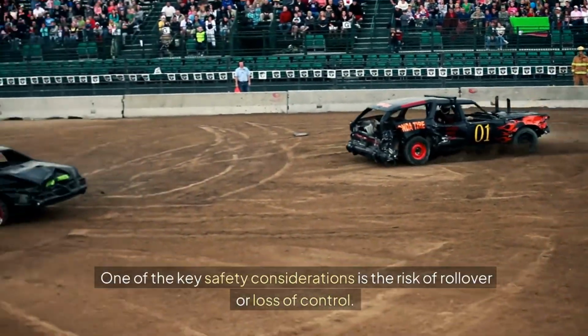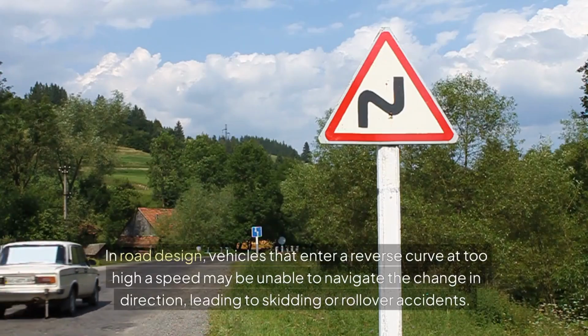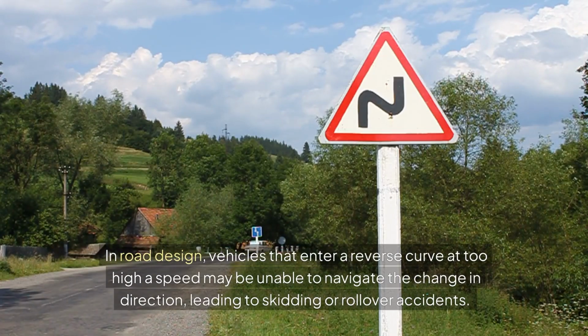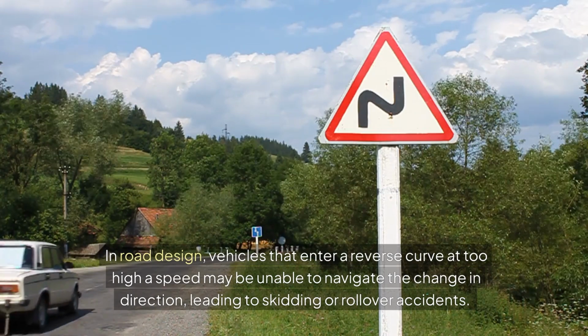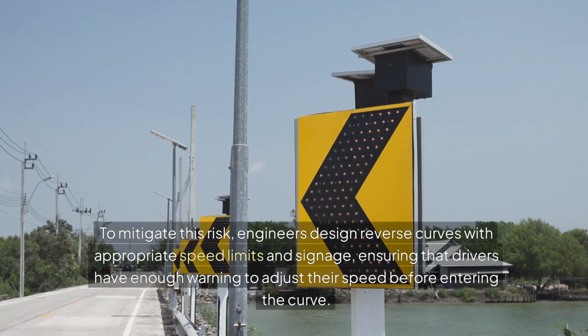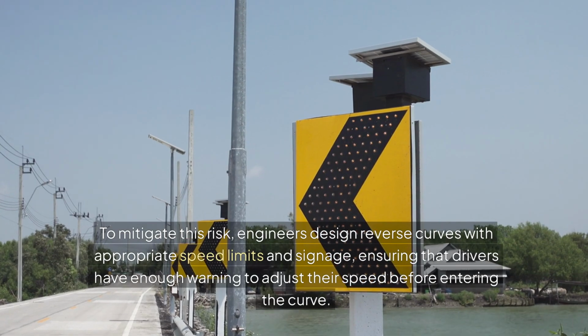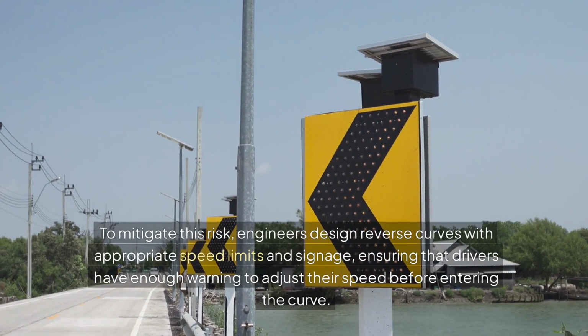One of the key safety considerations is the risk of rollover or loss of control. In road design, vehicles that enter a reverse curve at too high a speed may be unable to navigate the change in direction, leading to skidding or rollover accidents. To mitigate this risk, engineers design reverse curves with appropriate speed limits and signage, ensuring that drivers have enough warning to adjust their speed before entering the curve.